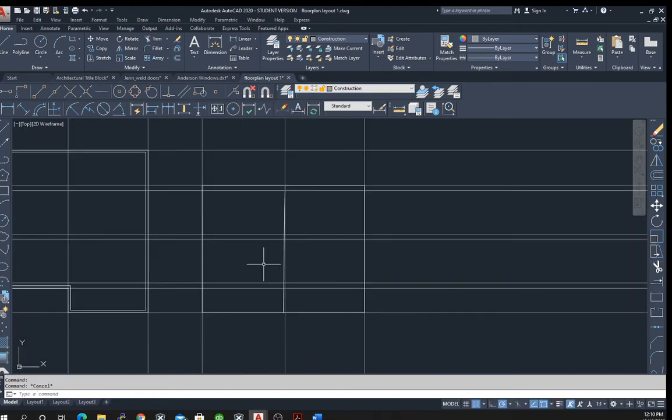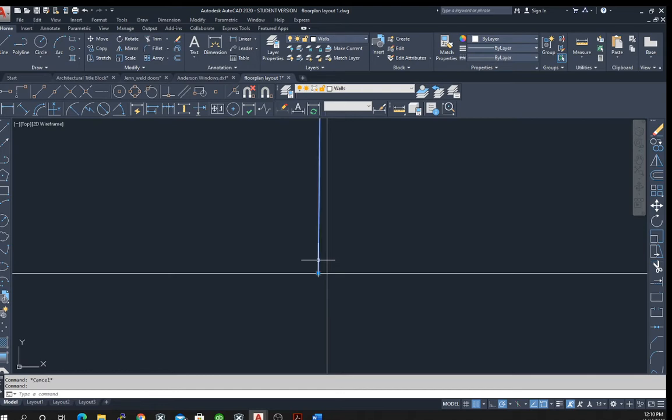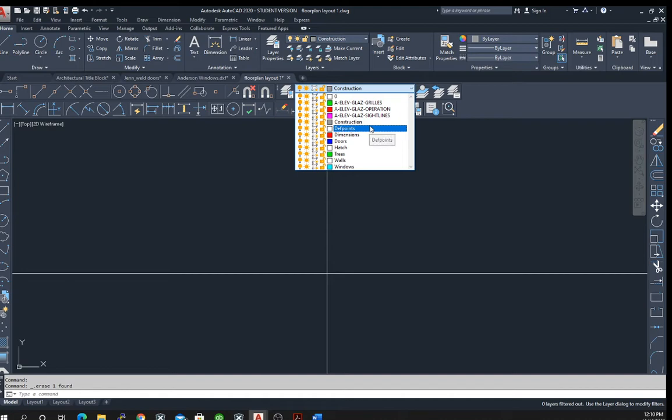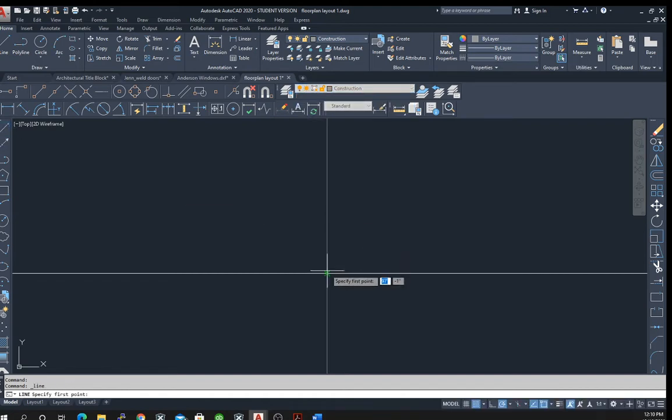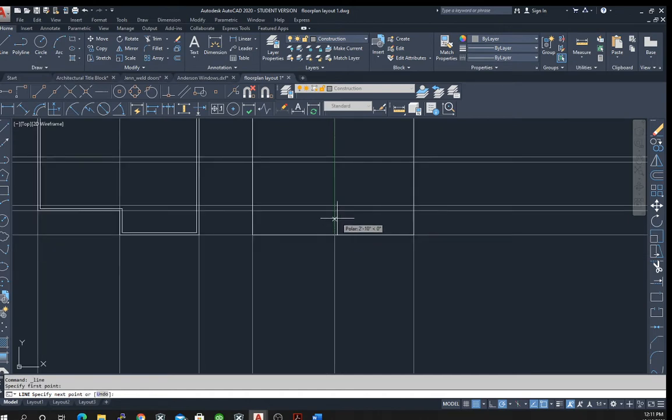So of course, but no, when I started, actually I didn't start on the intersection. So AutoCAD can be funny at times. This is why you always put dimensions in. You always use your dimensions as a final check to make sure that you've done everything right. Okay, so here's what happened that time. I actually started on my midpoint. Remember, your midpoint would be 15 and 15 feet, but this line is at 15.3. So that's actually why I started there.